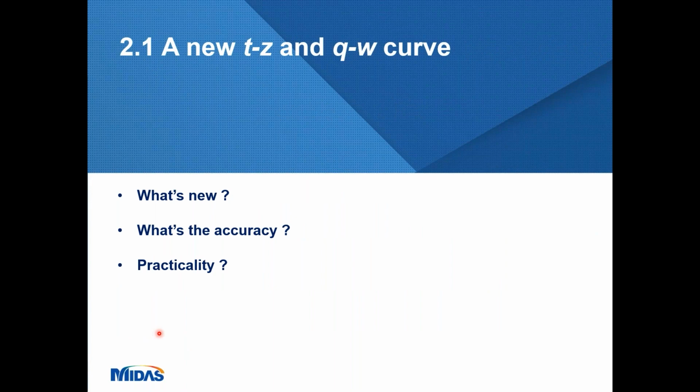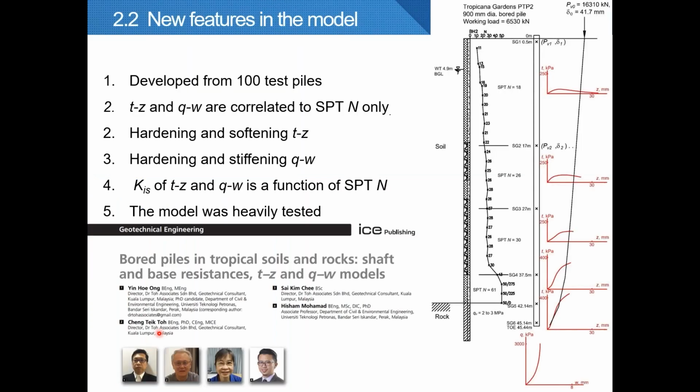Now, I'm going to introduce a new TZ and QW curve. I will explain what is new and whether it's worth for you to explore it. We have developed a new TZ and QW curve from 100 instrumented test piles. All of them are bored piles.